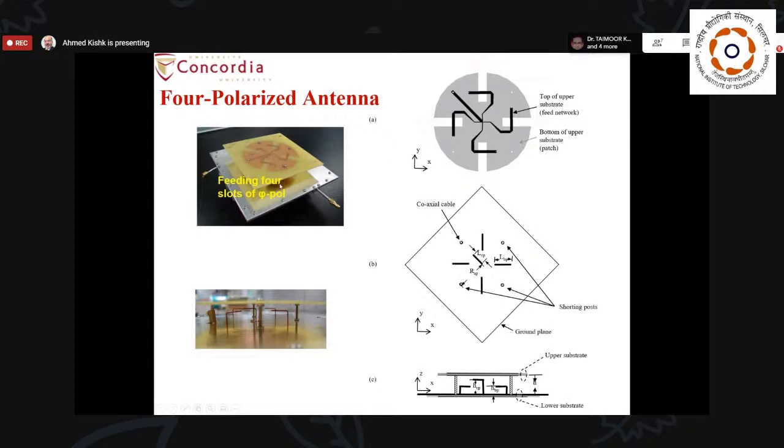This will be theta type of excitation. So both have a monopole type of radiation pattern, while the other polarization, similar to the one that we did for the air patch, has 2 probes against each other with differential feeding, and another 2 orthogonal to it. So these are the L-shaped probes. This is for this polarization, and this is for this polarization.